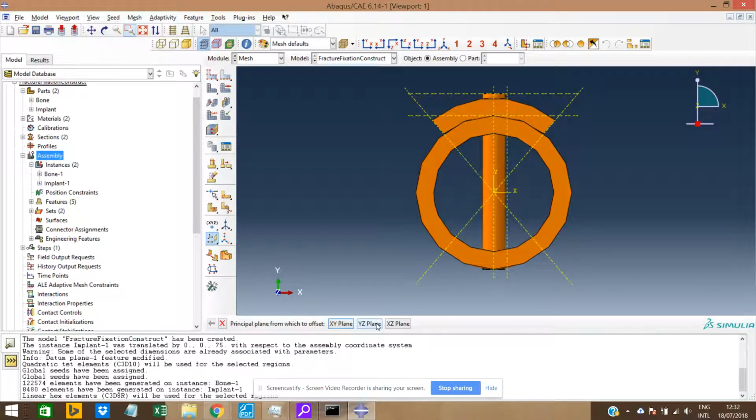This is because the screws are 2.5 millimeters in radius, so 3 is 0.5 farther. And doing these, I'm gonna enclose the screws in a little square, and you'll see later that in the mesh, this looks quite nice. It produces a nice mesh. So again, in the YZ plane, but this time -3, and you get another one here.